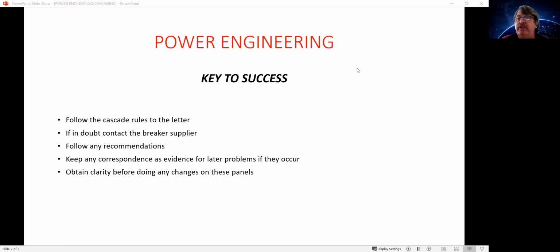The product range has changed every, I don't know, 12, 15 years about. So it's 20 years down the line. Would your new ranges comply with that? Because now you've got a breaker upstream and one downstream, and you're not going to find that easily. When these were sold, they came out with a package deal and the products were all new and in line with what was being provided. Going down the line, your replacement product possibly will not be available from the current offering.